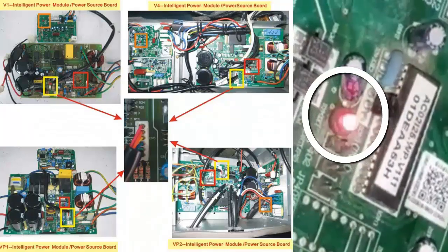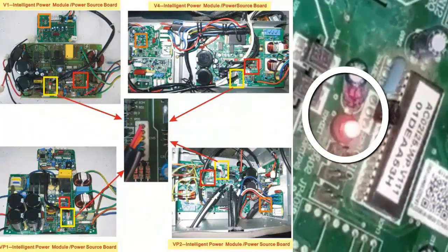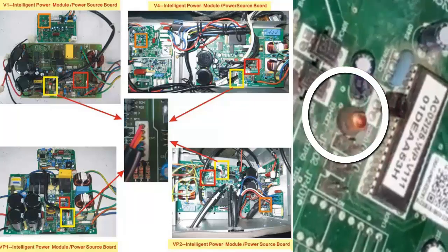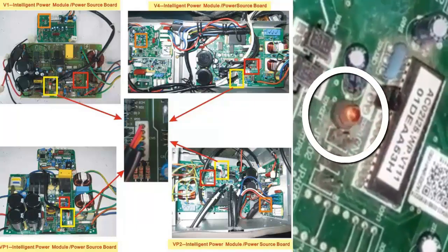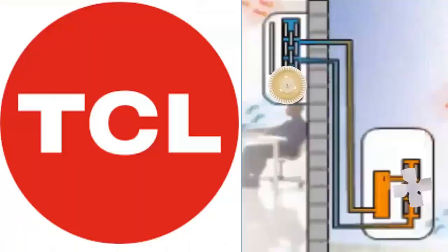6. If the error persists, observe the LEDs on the electronic boards. If a board does not light up, the problem is likely in that particular electronic module.